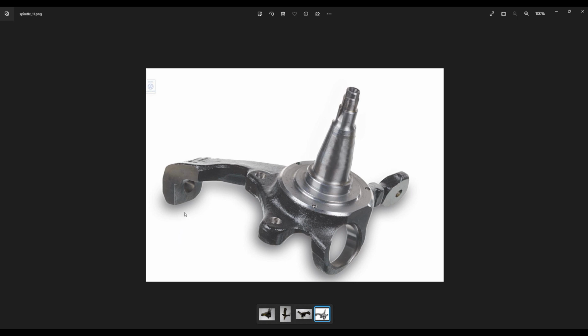Of course you need to be extremely accurate on this type of surfaces, and probably everything else doesn't need to be that accurate because it's not so important. It doesn't mean it will not be, but probably the accuracy you can allow to be 0.1 millimeter or even 0.2 millimeters from the surface.